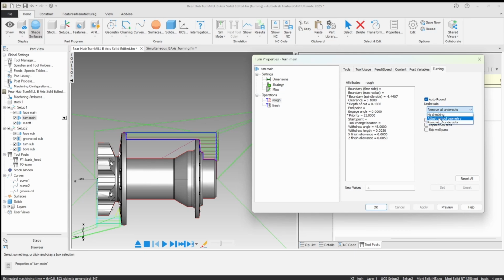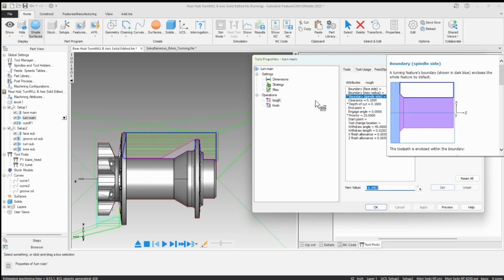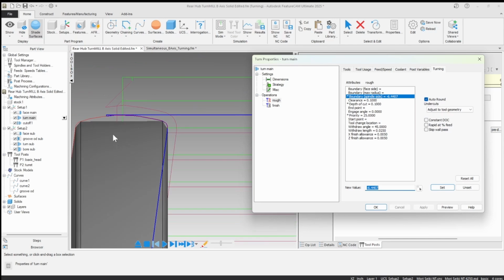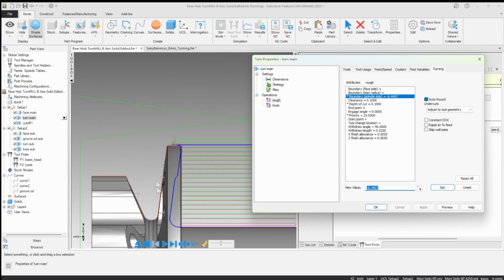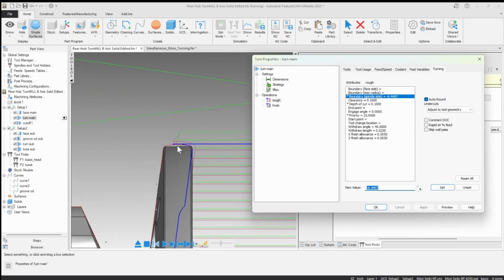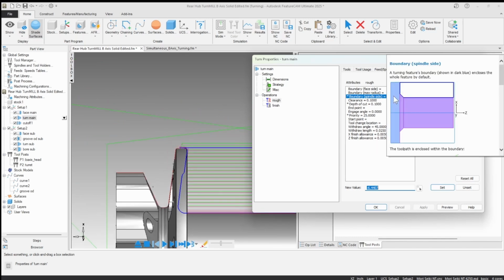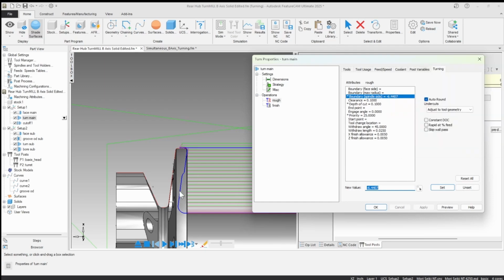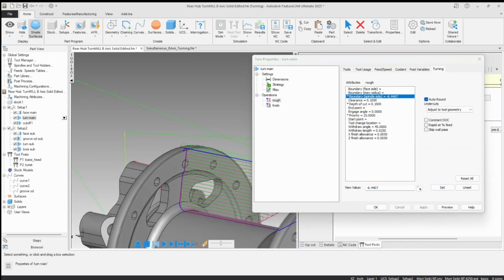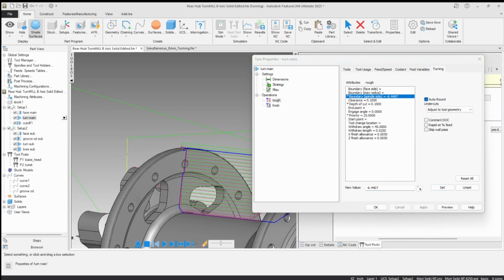So I want this to actually adjust and use the B-axis to help me out. So you can see all that it machined. We have this left. Then the spindle side boundary I have set to basically back here, just kind of over this radius on my part. And then you can see we're getting down in there. If I adjust that a little further, we might reach in here a little more, but you can see we're getting in there pretty close anyway. It looks like we're good.